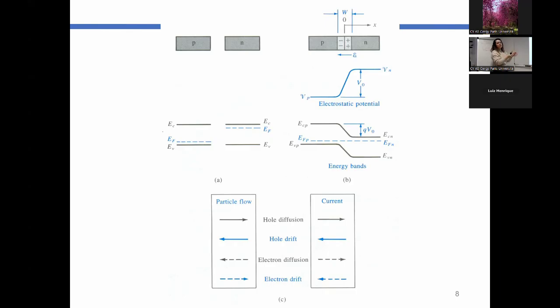So in terms of device physics, for interfaces, the Fermi level will be the parameter to set all the layers. So if you have, for instance, here metals and another junction, everything will be aligned in terms of the Fermi level. So here, the Fermi level is in this position.